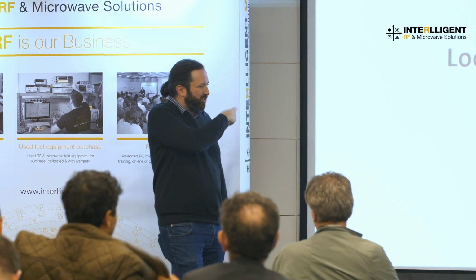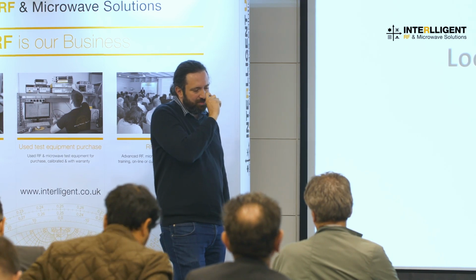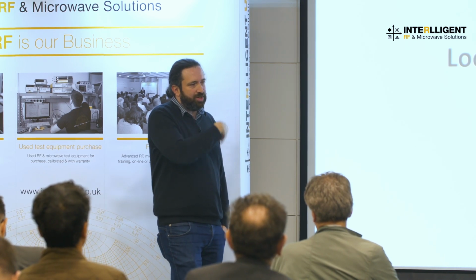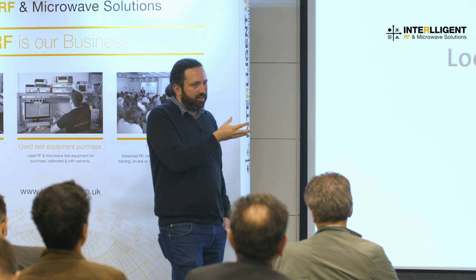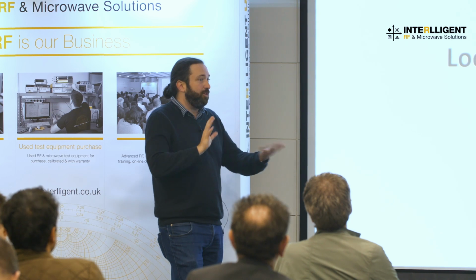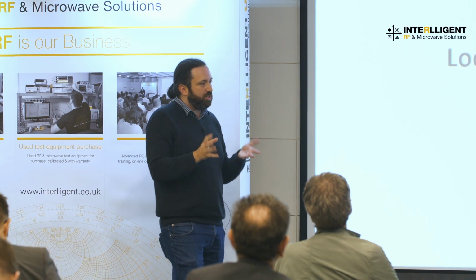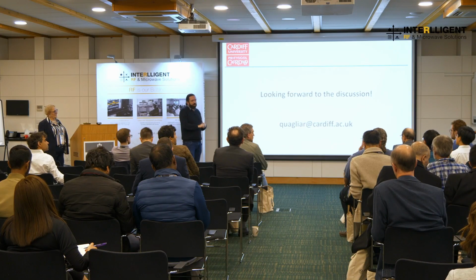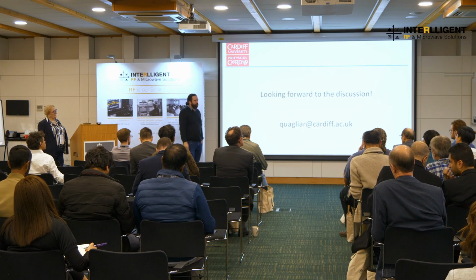Especially in the last design, the big one we used, we were able to access some of the advanced tools, like the STAN tool for stability analysis, because clearly in the Doherty the risk of parametric oscillation is very strong, and some of the devices we built did have that problem. And as usual, then you do the publication and say, I knew it was going to happen, but it's always the other way around.